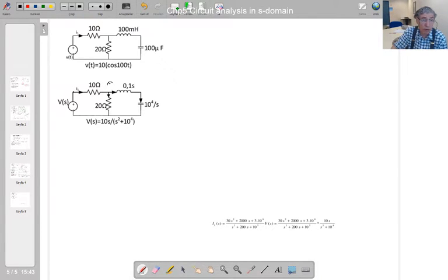That's the circuit given in time domain. This is time domain circuit. So we transfer this time domain circuit to S domain here. That has been done already, so I'm not going to repeat it once more. So if you see here, this is our circuit. In the classical method we are going to write 2NE equations. 2NE means NE is the number of elements in this circuit, so the total number of elements is 5. So altogether we are going to write 10 equations.